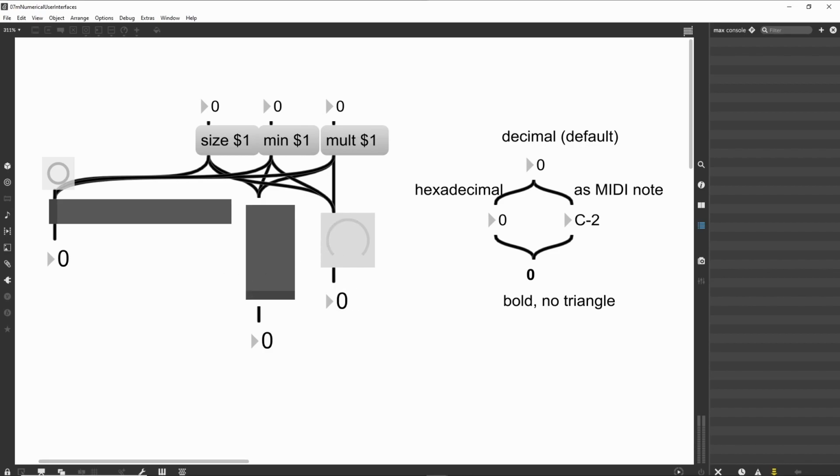Click and drag on the thumb of the slider objects to see the results displayed in the connected number boxes. The output of a slider is an integer number based on the range of the slider. Both the vertical and horizontal slider perform identically. The dial next to the vertical slider performs a similar function. However, in its current configuration, you need to move the mouse pointer in a vertical motion to change the position of the knob's wiper. This is something we will look at changing later in this tutorial.